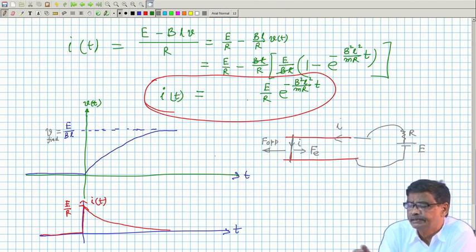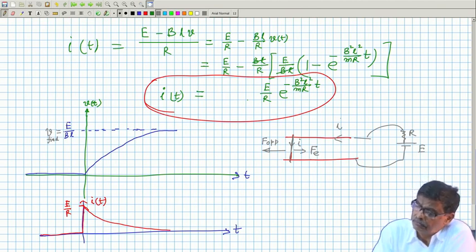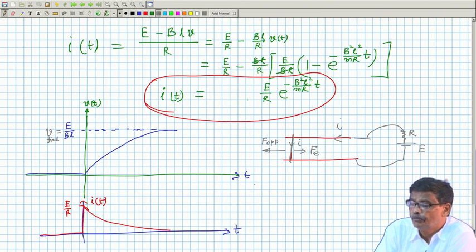Best way to think is that friction now appears. In general, on the moving conductor there will be two forces acting for the linear machines. One is the electromagnetic force, which is providing the velocity, and another is the force in the mechanical system, in the opposite direction.